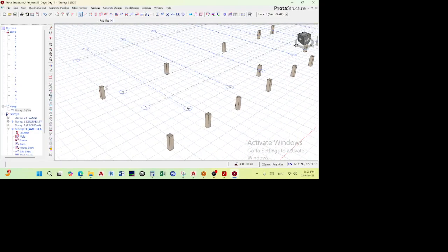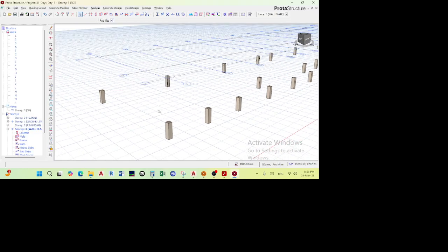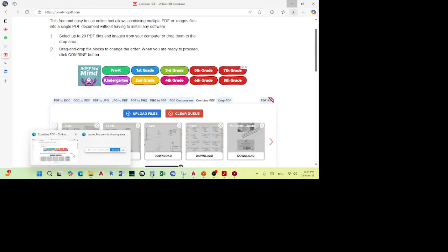So now, usually these design softwares, and also according to what a friend of mine, Mark, told me, when you're placing structural columns, not those architectural pillars, the way that design softwares read them is that you are placing from the top and it's going to the bottom, as opposed to architectural columns or architectural walls where when you place it, it reads from the bottom and going to the top.